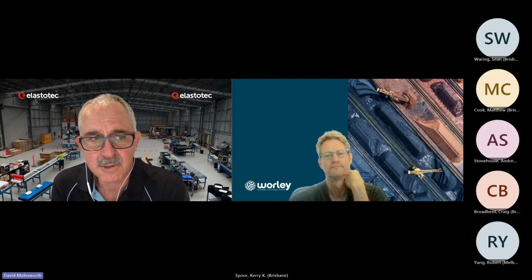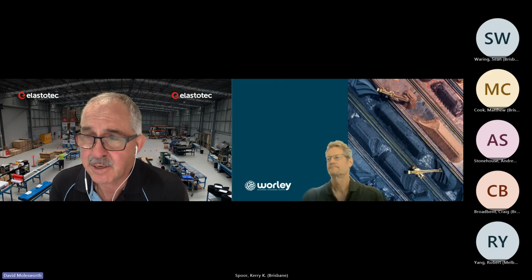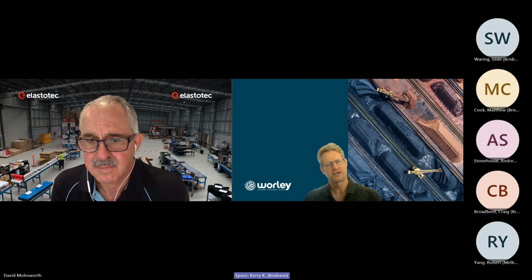So we don't go to a full 80%, which is quite rigid. This is either what's called a single row ceramic or a double row. It's around the 40% ceramic mark. And with a thicker rubber backing, not the 12 mil. It's typically either a 15 or a 20 mil. And hot vulcanized, not cold. Like any of these pulleys that are in demanding applications where you want long service life, they have to be hot vulcanized. And that's to do with the fatigue strength of the rubber.